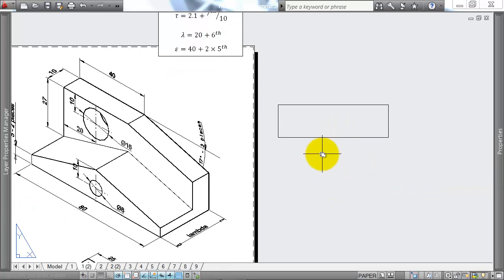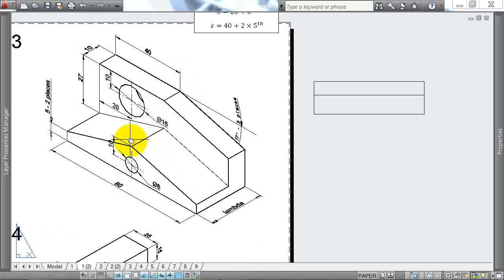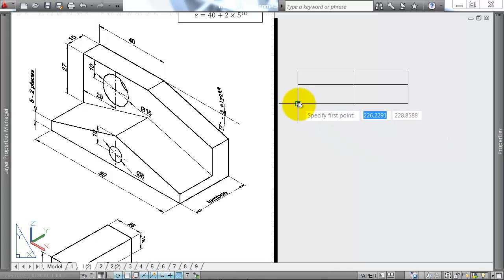Close. I've got this line along the top, so if I'm looking down from the top of this shape, I'm going to see this 10. So in 10 units, and that goes the whole way along. 40 units across, I've got this peak, and this is a symmetrical portion of the shape in the middle. So that peak, 40 is half of 80. So that symmetrical peak is going to appear from the top view as one line the whole way through. What else do we have? So we've got circular features, but I'm not going to worry about them just now. Let's go on to the other view and then locate the circles.